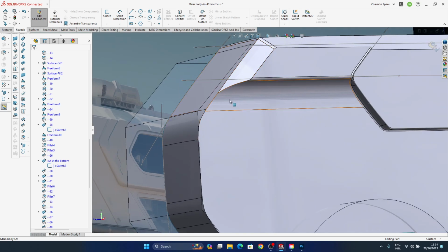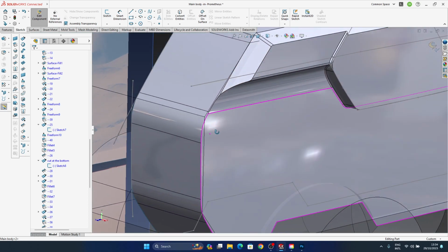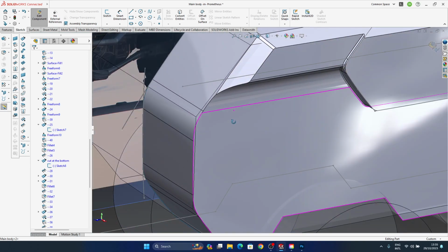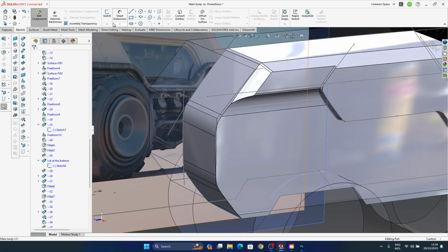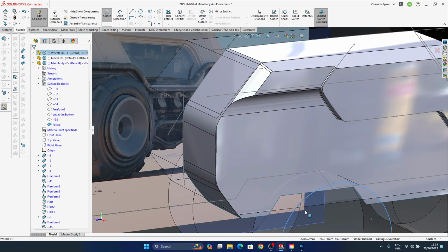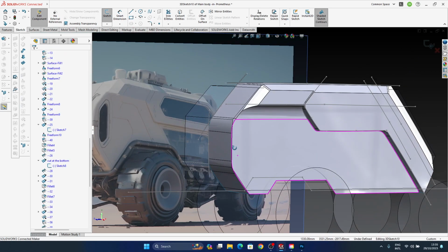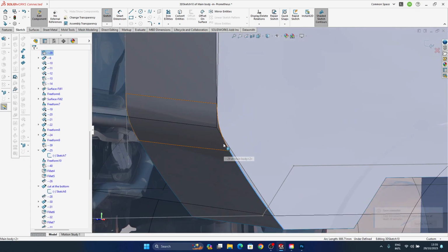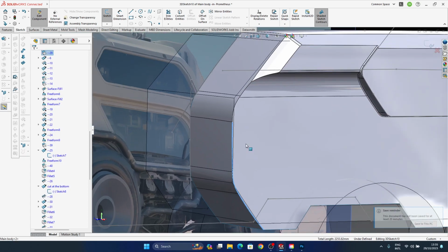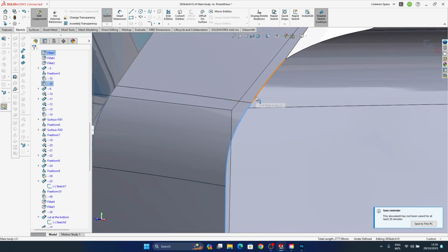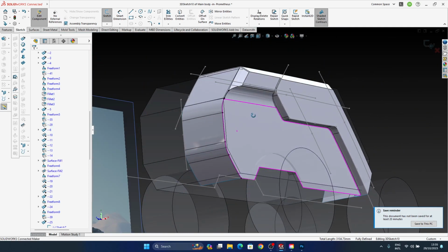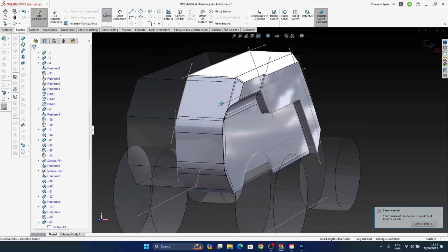All right, so if I'm creating a curve to use for a cylinder, let's go into the 3D sketch and create a curve by converting entities. So this, this, this, this, and this. There you go. So I'm converting this into a curve.